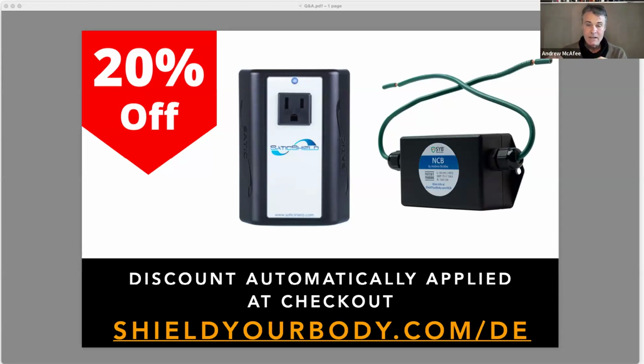You can use isolation transformers if you must to keep it out of the noise of your house. There are numerous solutions, but you have this current flowing on the grounding system from the variable frequency drives that you need to allow to get out somehow and not contaminate the rest of the house. So now we're getting into strategies.